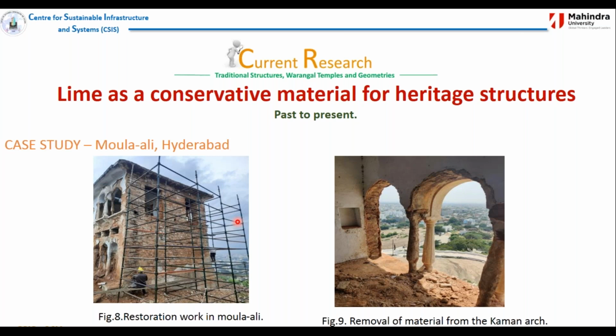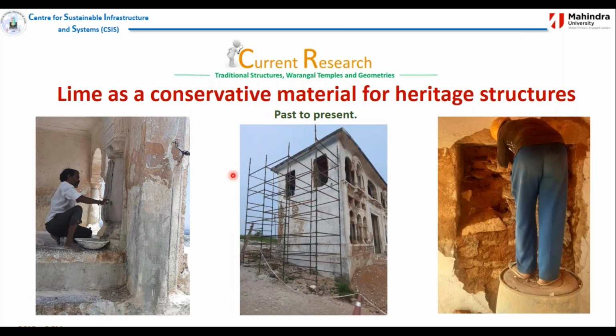So we found one person who belonged to the family of Charminar, and we found the lime mixing. They store lime for 1 month of fermentation of the lime. They mix, and we also use different materials, which I'm going to show. So you can see certain places where they have filled with the red mud and stones. We have removed everything.